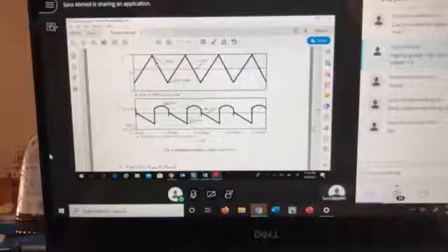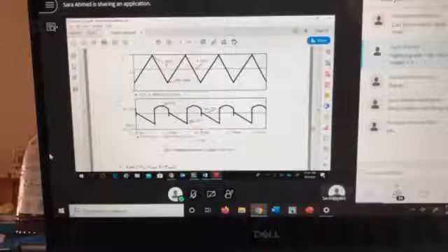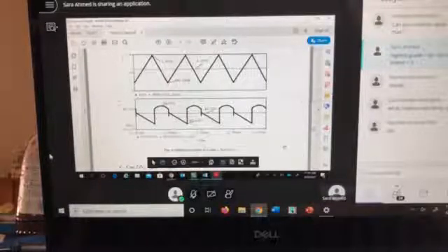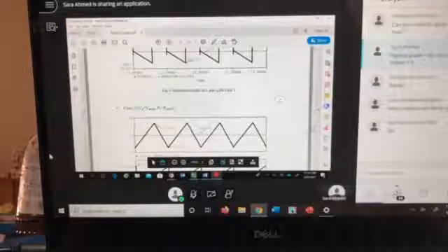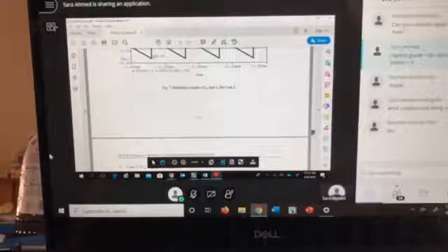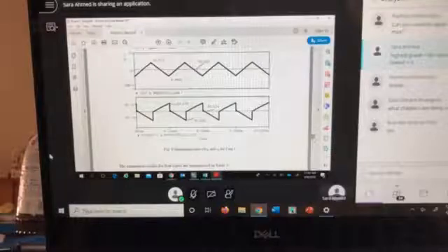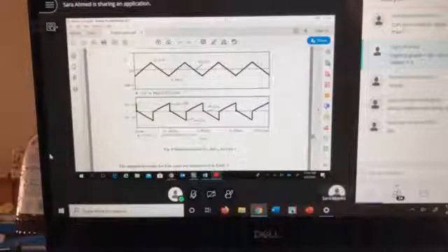And if you're not able to do that with the software, it was okay to write it on top of it, either by hand or in Paint or whatever, just to show the numbers on the on and off values. Again, you're going to repeat it for different cases. All you change in your simulation is the duty cycle, the input voltage, and the output power, which is your load.